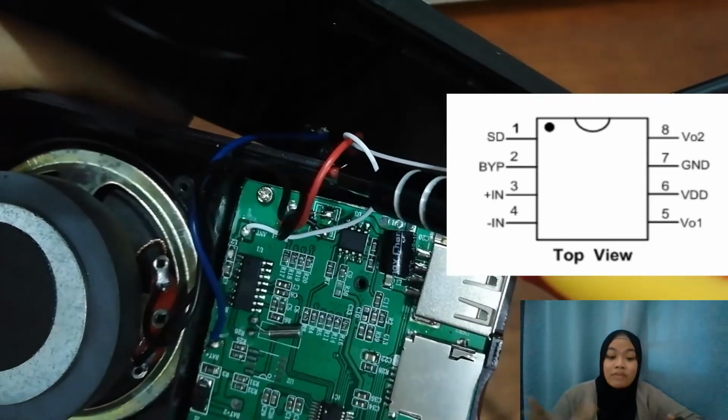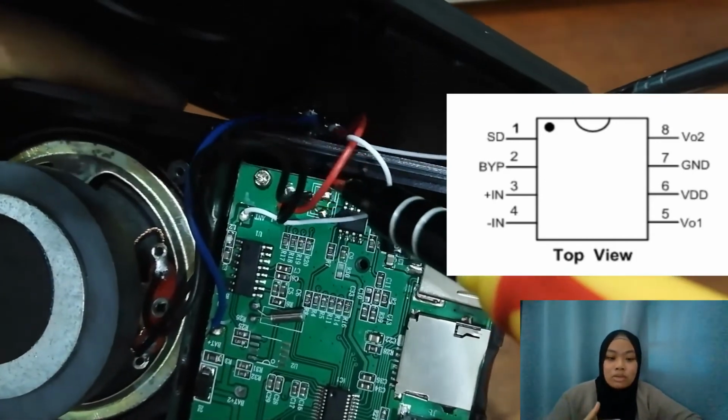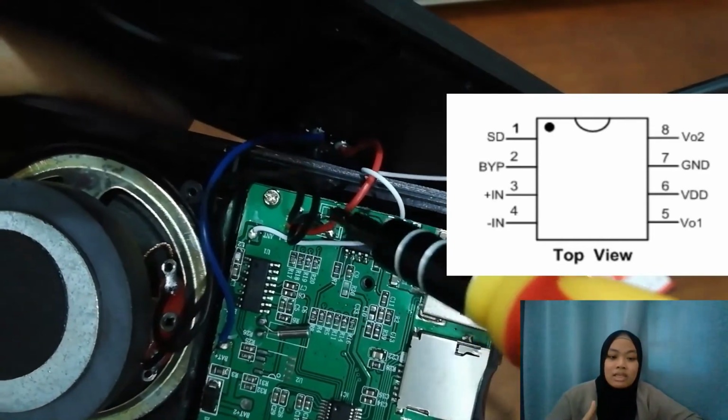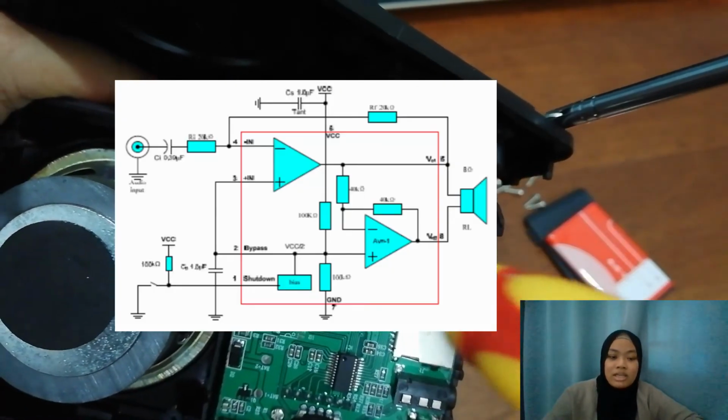Pin number 5 is the negative output. Pin number 6 is the analog VDD input supply. Pin number 7 is a ground connection for circuitry, and pin number 8 is for the positive output. So here is the circuit layout inside the IC.